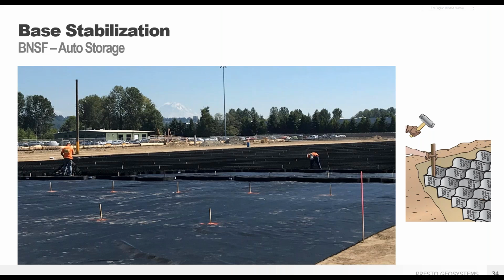Another technique tip important for large projects is to prep the site layout. This contractor wanted square panels for the entire installation, so they surveyed and staked the corners for each GeoWeb panel over the 25-acre site. Once the GeoWeb panels were filled, they just pulled the stakes. Similar to using stretcher frames to open panels to a set distance, this made such a large installation go very quickly and very efficiently.